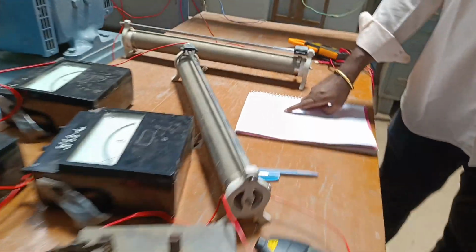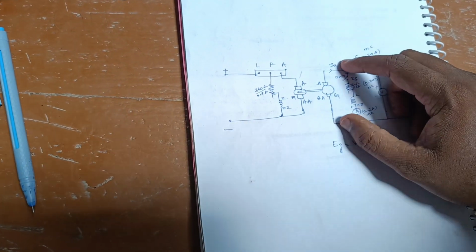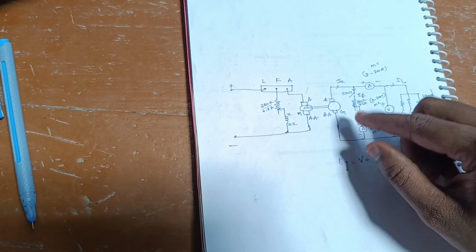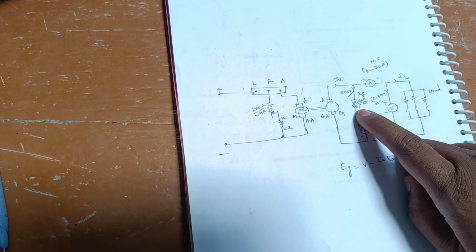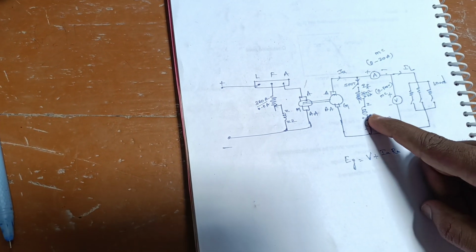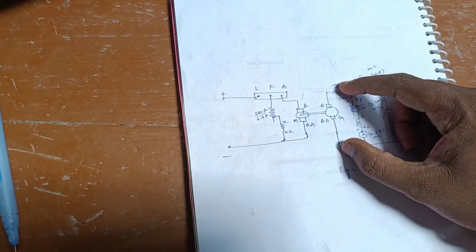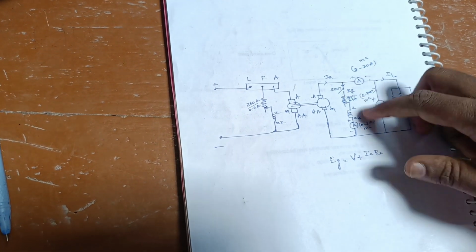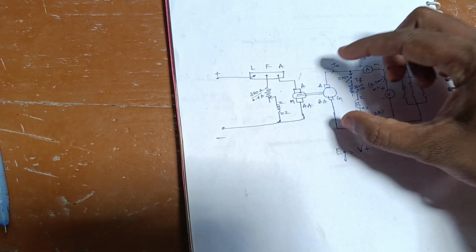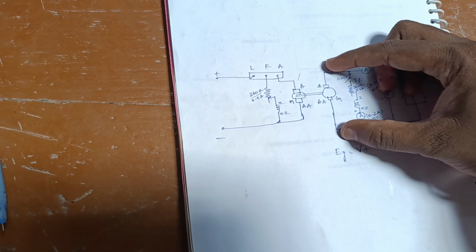When the field circuit is opened and I start the motor, a small amount of EMF is induced in the DC generator. This small amount of EMF is induced because of the small amount of flux stored initially, which is called residual magnetism. When I close the SPST switch, there is a provision for the field current, and then the maximum amount of EMF is induced in the DC generator. That we will observe by conducting the experiment.